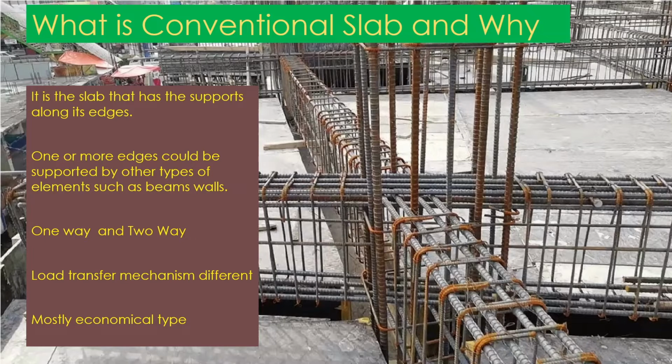Now, depending on the behavior or the load transfer mechanism, there are two categories: one way and two way. In a one way slab, load transfer will be in one direction. In a two way slab, load transfer will be in both directions. The span ratio, shorter span to long span ratio, is considered to differentiate one way and two way slabs. Slabs having a long span to short span ratio equal to or smaller than 2 are called two way slabs.